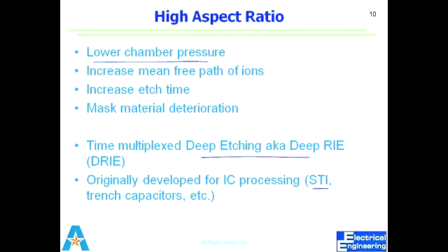But the higher the selectivity of that species with respect to the film, the lower the damage would be. Similarly, it depends on how much time you are etching, whether you are over etching or not. If you are over etching the surface, we will discuss what over etch is, in that case the damage would be higher.